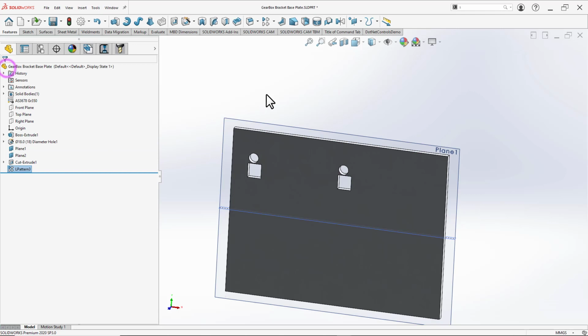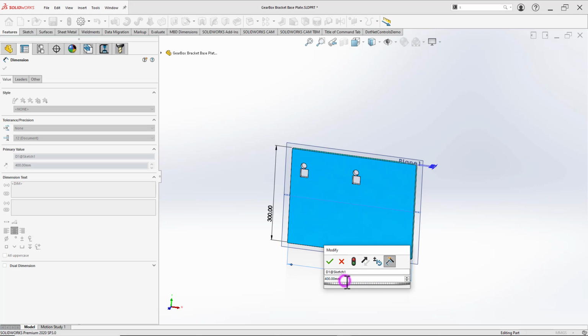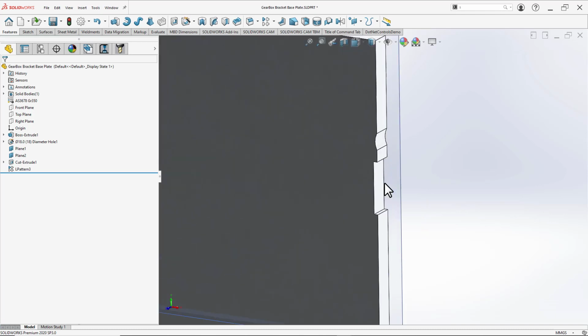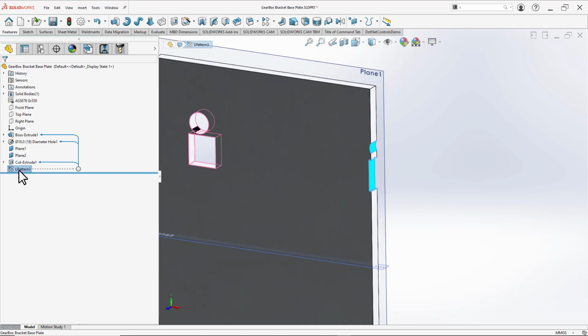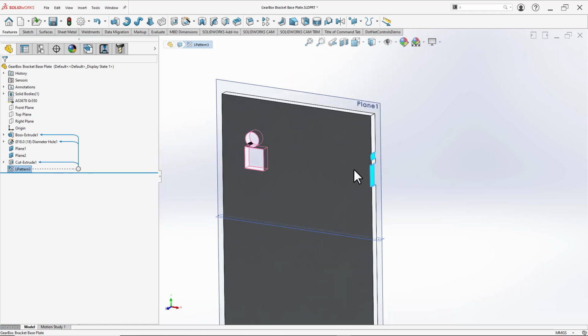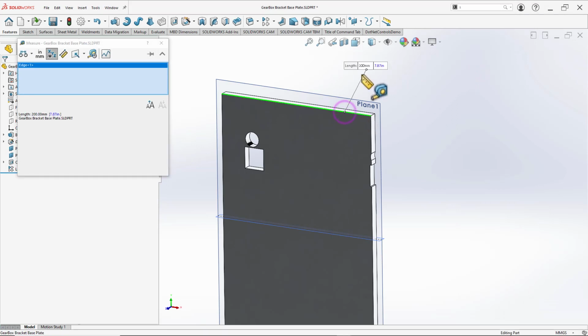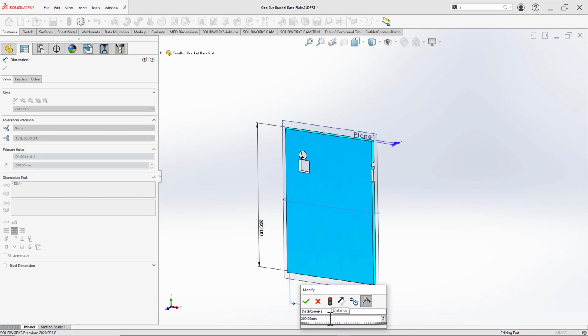The problem with that is that if I use that feature, once I change the size of the plate to say half of what it is now, look what happened here. So this last feature kind of was cut in half. What happened is that SOLIDWORKS says you wanted the distance between these two instances to be 168 millimeters, but the width of the part itself is just 200 millimeters. So that's what happens. It just makes sense. You simply don't have enough room.